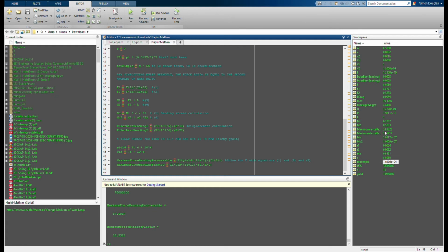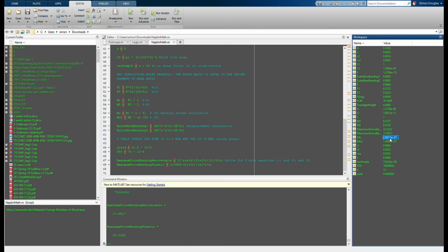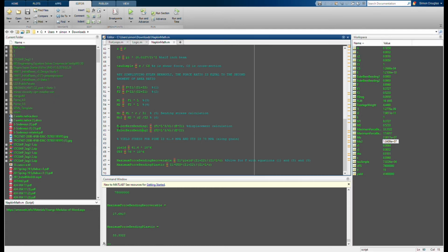Our stresses came out to be, here on the right side, about 20 megapascals, and about 10 megapascals for the smaller dowels. And that is because what I solved for was the Euler-Bernoulli. When I equated the forces, I assumed that both of the beams will bend to the same displacement, and so the larger beam will end up taking a lot more force.